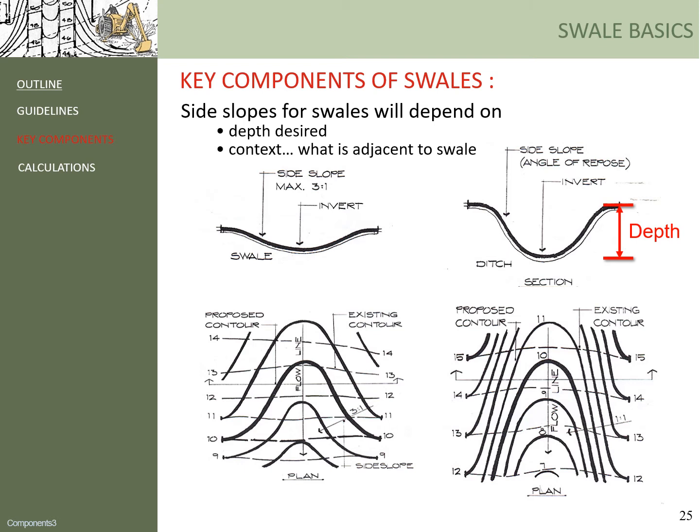But before we move on to the next slide, I just want to point out that from the contour patterns of swell versus ditch shown on the plans here, you can see the contour spacing of the ditch is much closer than those of the swell on the sides, right? Although their center line slope can be exactly the same, as indicated by the same contour spacing here.